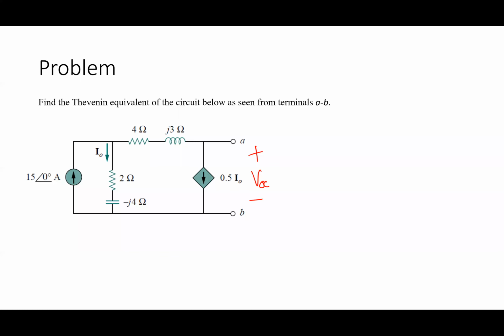You can't do that here, because you're screwing up the circuit. I naught is the current through a branch that you're going to end up moving around if you do the source transformation. Correct. So in this case, I'm going to leave it there. Anytime I'm doing things with dependent sources like this, I don't do any simplifications like that. If I thought hard enough, there might be some cases where you could, but I don't want to, because I know I can make a mistake. I know I'm a simple man. I keep things simple.